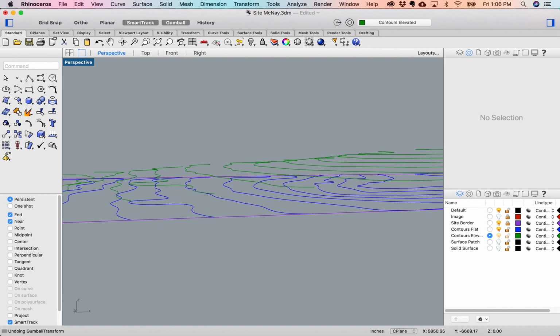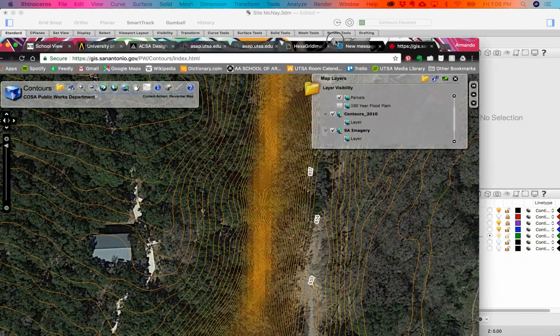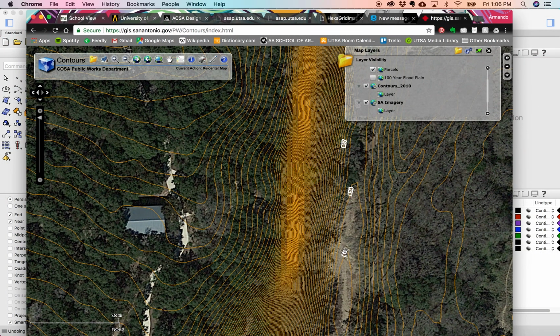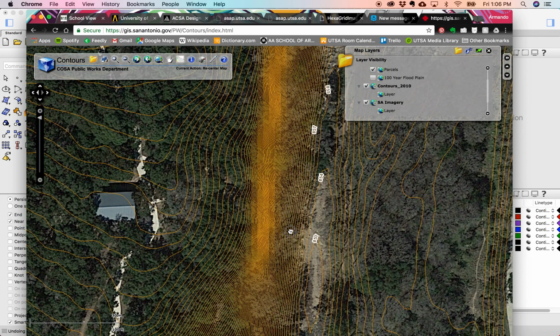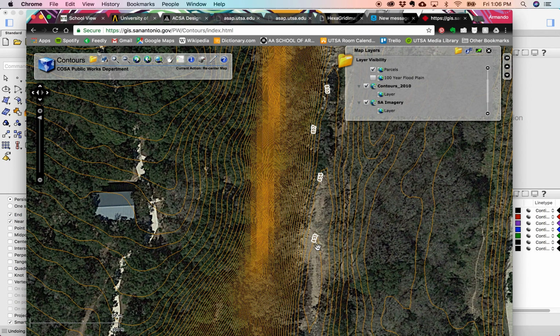So in order to find the distance for yours, if you go back to the original map, you'll see the line at the bottom. This is 853 feet, and the next one is 854. So these lines are set at 1-foot increments.